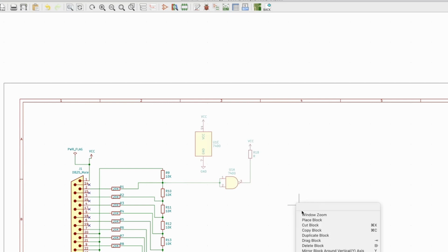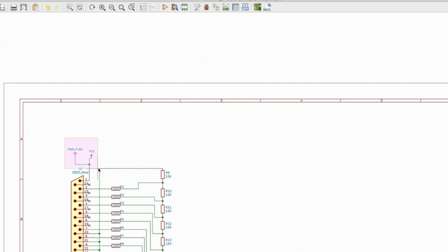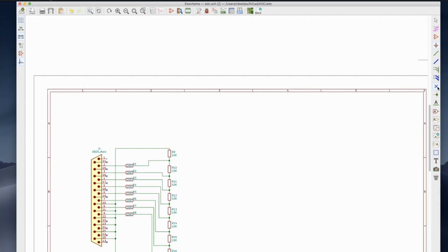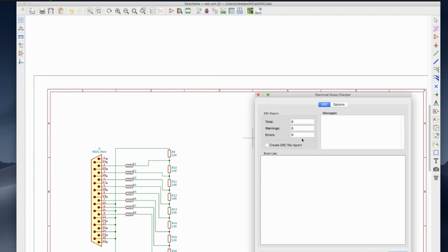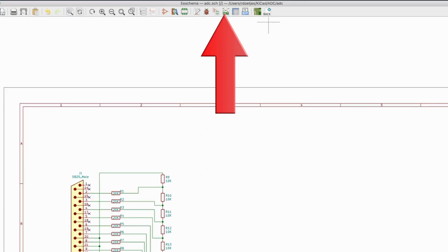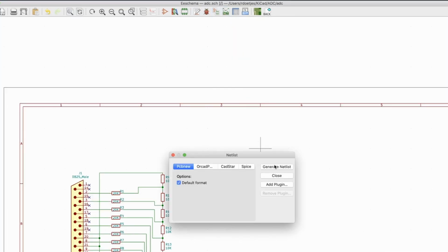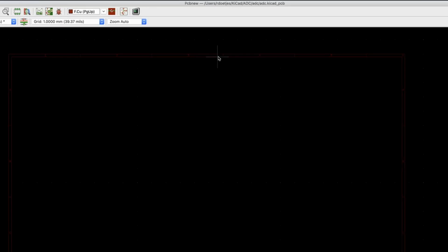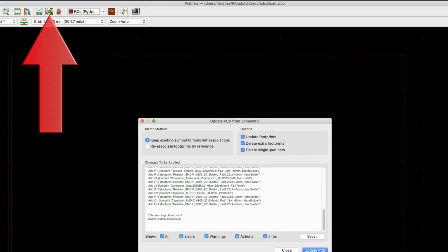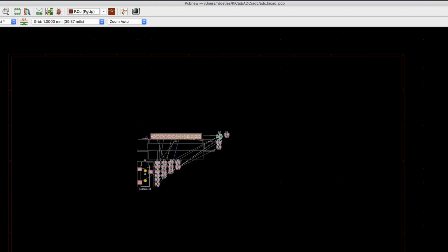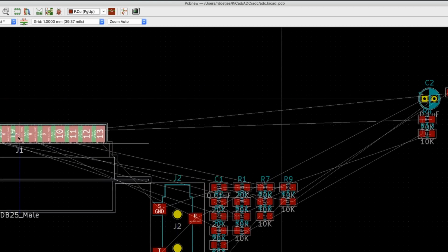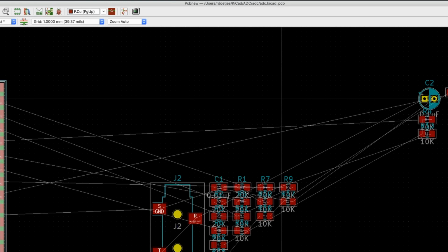Now let's move this because we're not going to use that. Delete. And this is how quickly you can actually draw in KiCad when you have these shortcuts down. Let's run this again, that's good. Let's run the net again. Generate netlist, okay. Right, let's go and make the PCB now. Let's import it again. Update. Close, okay. Let's press M for move. Hover over the component and move.